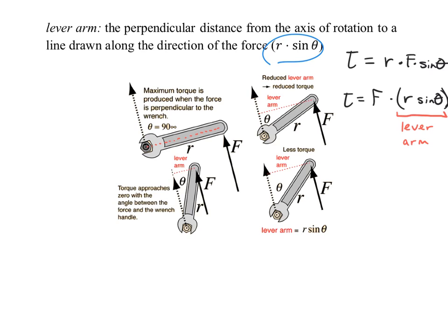So what's happening is this. If we want to get more out of our torque produced, we want our theta value to be closer to 90 degrees. Take a look at the first diagram. Although we don't see it, there is a right angle right there. So this angle is 90 degrees. Then this next angle is, let's say, maybe 70 degrees. Well, if that's 70, then this theta in here is also 70.